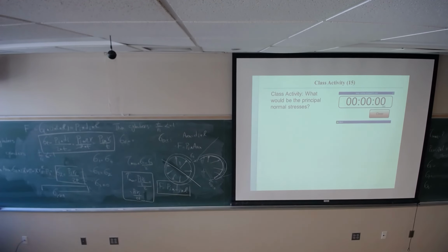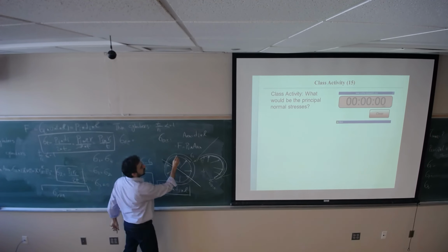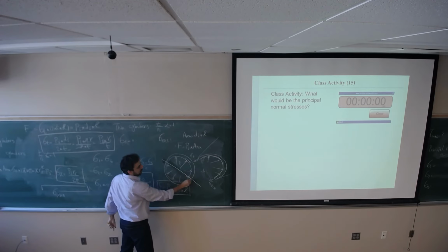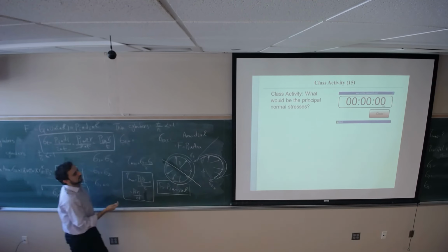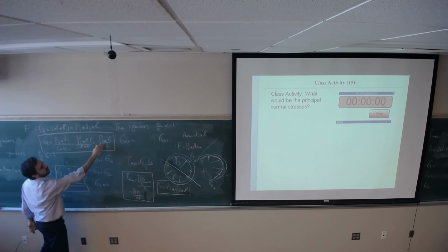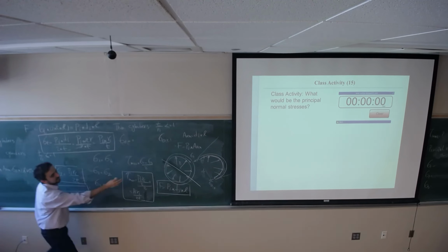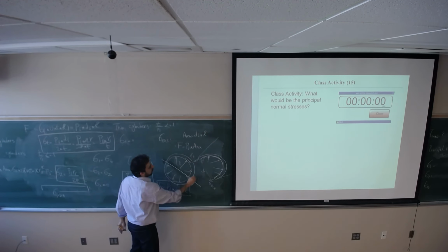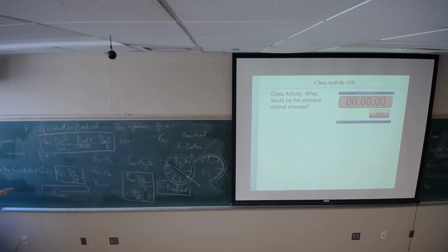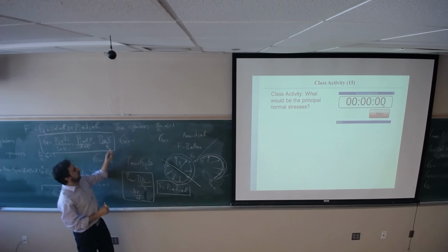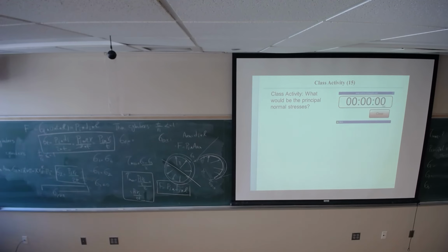And as you see, for any point, it doesn't matter what R is, because it's a thin wall, so we assume that the radius for all points on the wall is going to be the same. We don't have different values of stress for different points. So any point in this thickness, in the cross section, is going to see the same sigma theta and sigma z, if there is a cap.